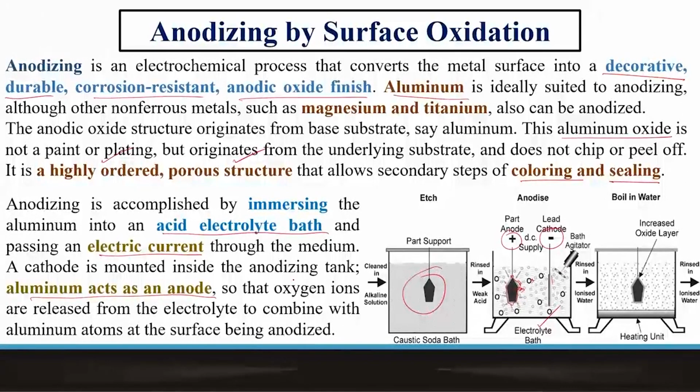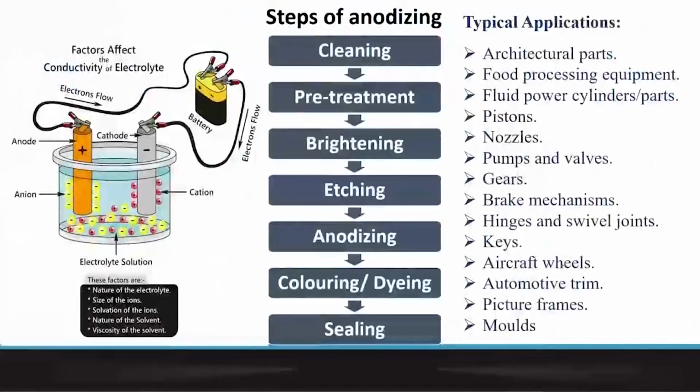If we wanted to create alumina out of aluminium, the answer is very simple: when we create this alumina layer, it is only a very thin layer on the surface, but fairly adherent. And in the process, this Al2O3 layer on aluminium can protect aluminium from further degradation during use. Degradation means converting the metal into its oxide. We are doing that beforehand so that no further such degradation happens during the applications, during the use.